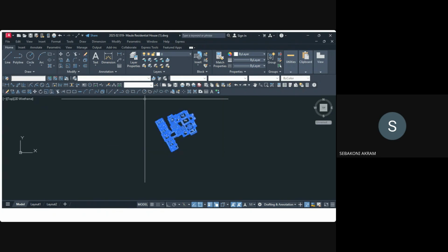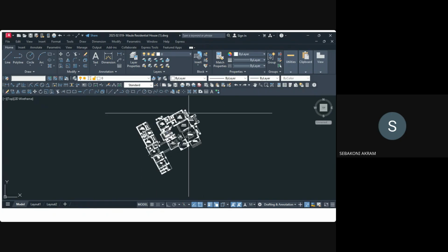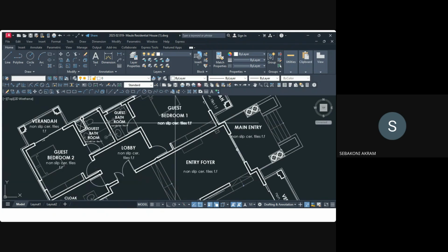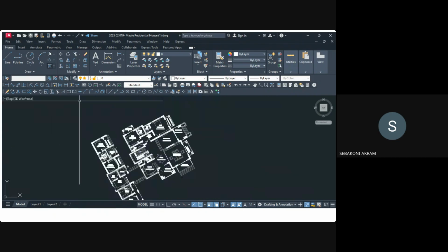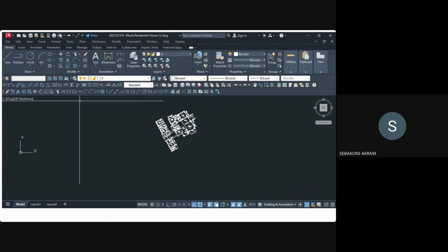So you highlight this now. We are going to clean this. You explode. What is the importance of exploding? It breaks a component, or a solid part of a drawing, into different parts. So when you explode this, you'd come back to this drawing and you'd find that you see these words initially. Before, let me Control Z, let me undo the exploding here.